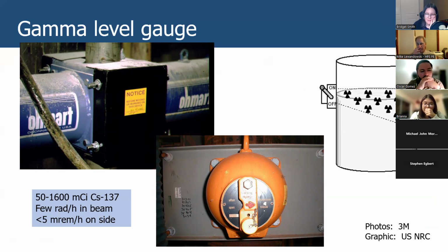And we can measure the unattenuated beam, I naught, and then put some material in between and measure the attenuated beam, I, and then we're able to derive the thickness, or quite simply, we could sense the difference between having nothing in between our radiation source and the detector and having something in between. So this is the first application of something which might be called a level gauge or a nuclear switch.